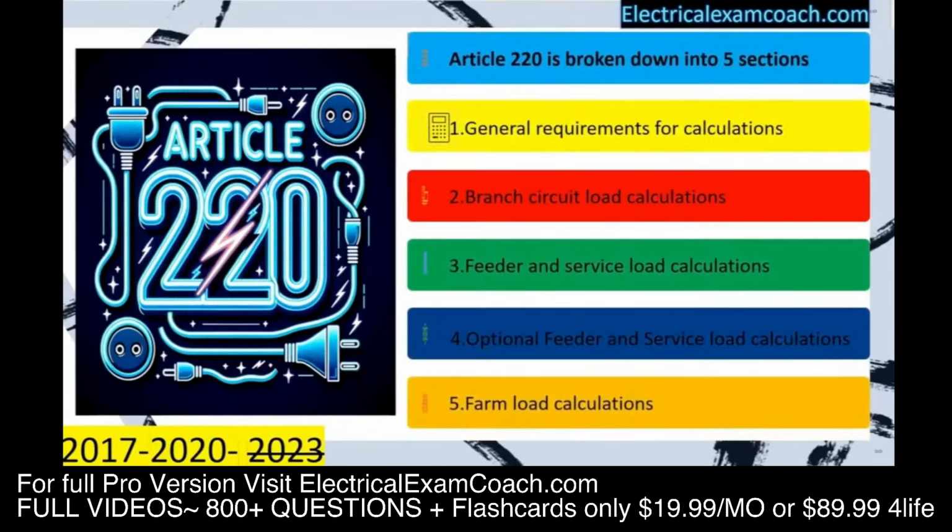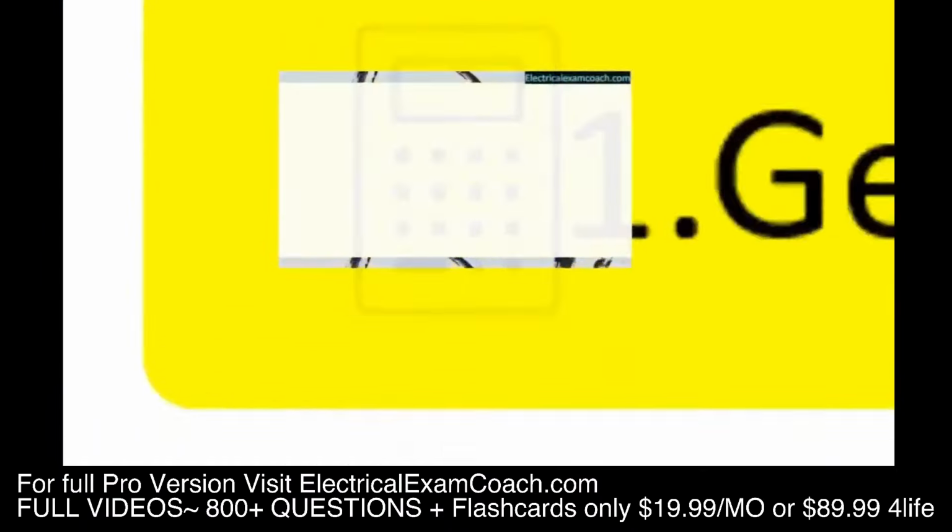Article 220 is broken down into 5 sections. The first one is general requirements. The second one is branch circuit load calculations. The third one is feeder and service load calculations. Part 4 is optional feeder and service load calculations. And Part 5 is farm load calculations. We're going to take you through each one of these piece by piece, except for farm load calculations. The odds of you ever being tested on that are very slim. And if you are, you'll be able to apply everything that I am going to teach you and roll it into a farm load calc.